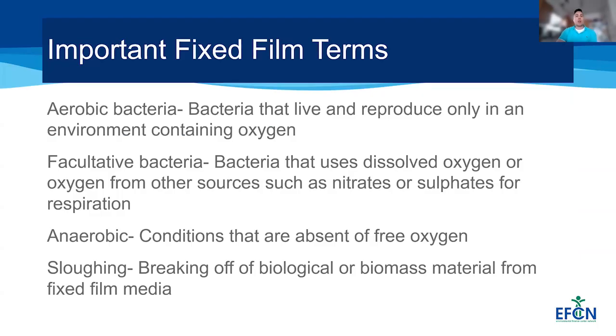Now, just a couple quick terms I want to make sure we're familiar with, and Tucker did touch on some of these as well. The first one is aerobic bacteria, and these are bacteria that live and reproduce only in an environment containing free oxygen. Then there's also facultative bacteria. This is bacteria that uses dissolved oxygen or oxygen from other sources, such as nitrates or sulfates, for respiration. These bacteria in our wastewater treatment processes prefer dissolved oxygen, but can also use other sources when dissolved oxygen is not available. They can live in aerobic or anaerobic conditions.